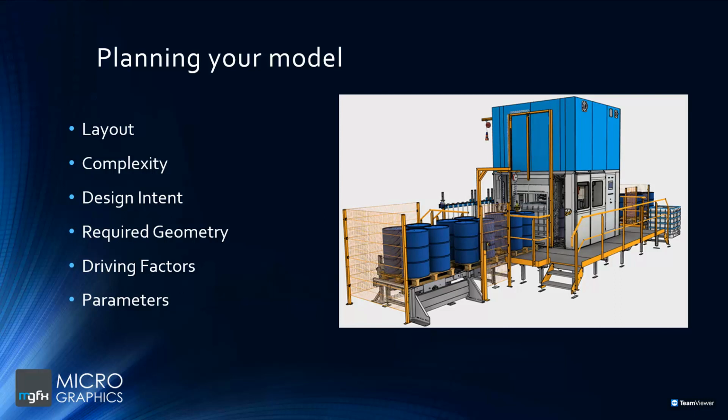We can pick that out as something important and include in that reference. Once again, the height of the opening going into that machine is driven by the height of the barrel on the pallet. So there's a parameter or a design constraint there that needs to be met.